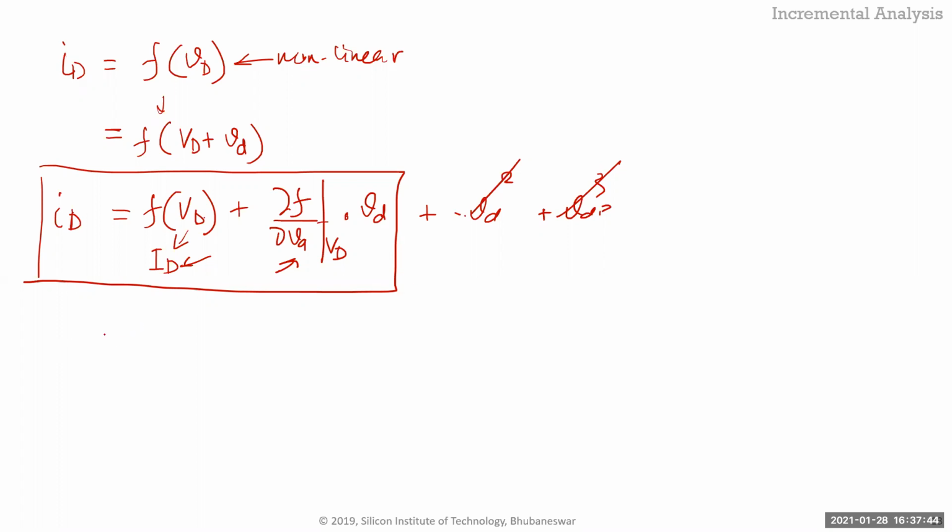Okay, so for example, let's take the diode equation again. ID is equal to some IS times e to the power VD over the thermal voltage, which is obviously kT over q, right? So I can, okay, I should write this as capital V, right? Which is equal to IS times e to the power the DC value, and then the small signal I'm giving on top of that, divided by VT.